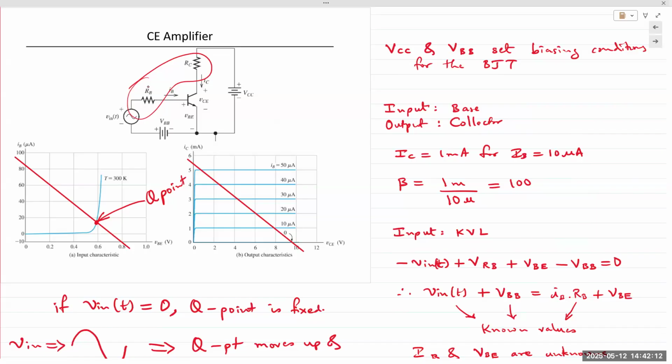The beta of the transistor, whether it's the same make and model, varies wildly. As an example, the transistor we used in our labs, 2222 or the 3904, can have a beta ranging from about 30, 35 all the way to 200. Okay, so you could have two transistors in your lab kit. The amplifier would work with one of the transistors. If you plug in the second one, it may not work, or it may result in clipping or distortion.